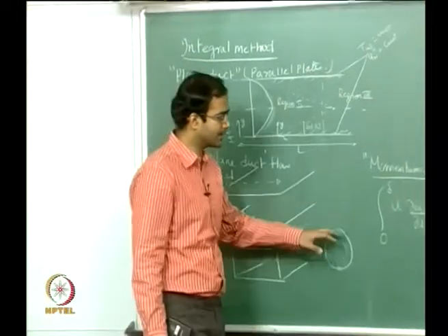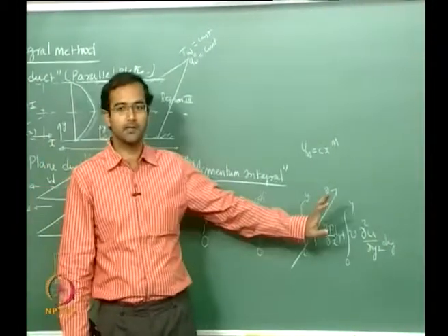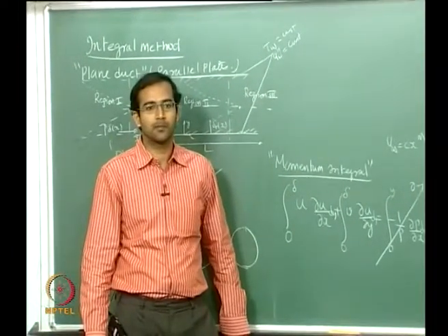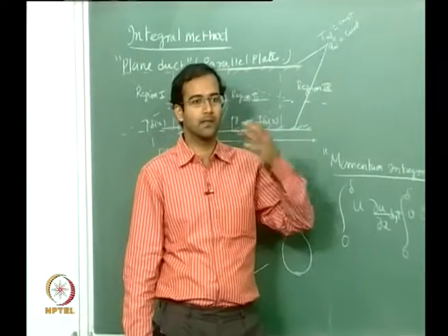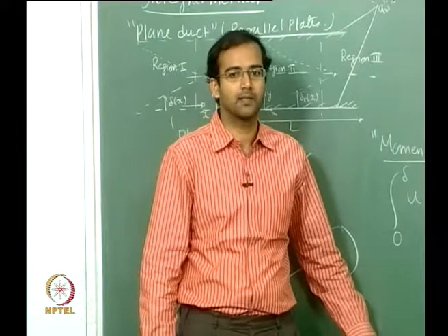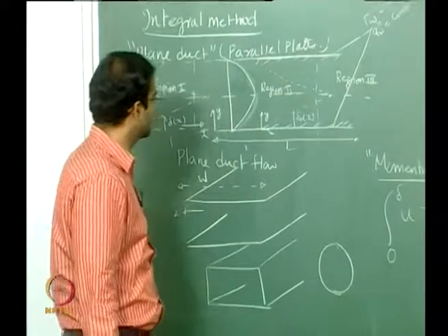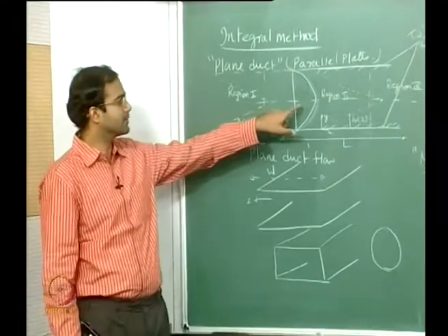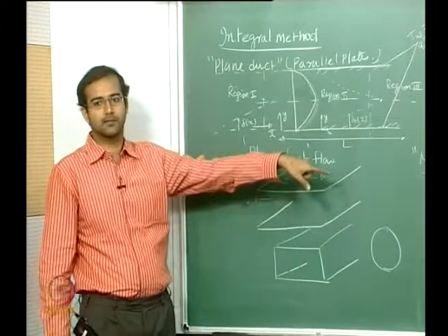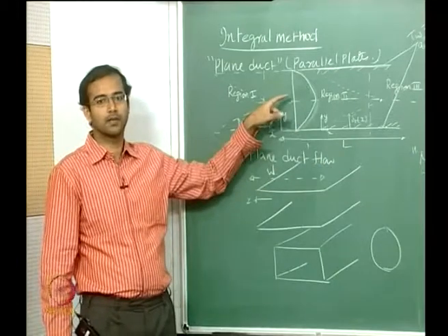So if you look at the initial part of the boundary layer development, you can make an approximation that this is 0 and this is now a flat plate flow past a flat plate. The same way that you did the momentum integral there, the same thing can be applied, but this will be a very big crude approximation, and you cannot get an asymptotic solution for the fully developed case from this, because the momentum integral is not valid for the fully developed case.